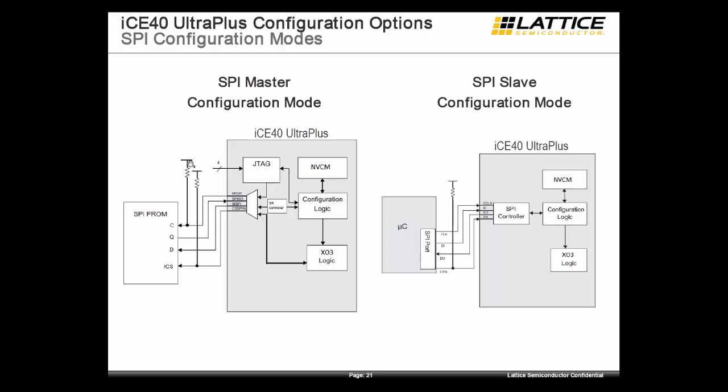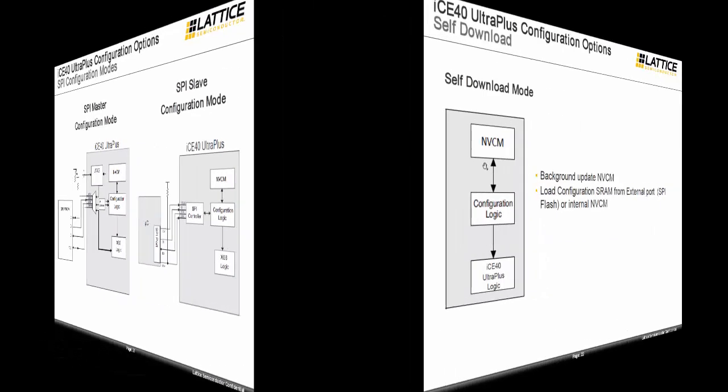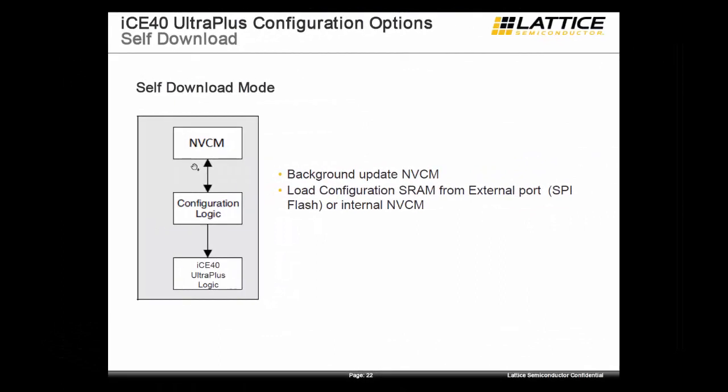The NVCM programming memory and the SRAM configuration space are accessed through the SPI controller. So everything can be programmed through this one interface. There is a self-download mode available when the non-volatile configuration memory is programmed, and that happens when the device is powered up.